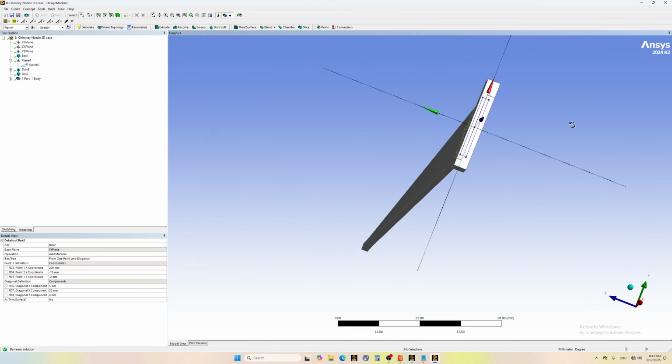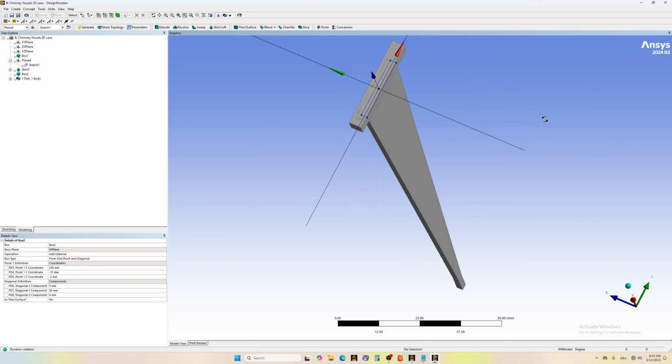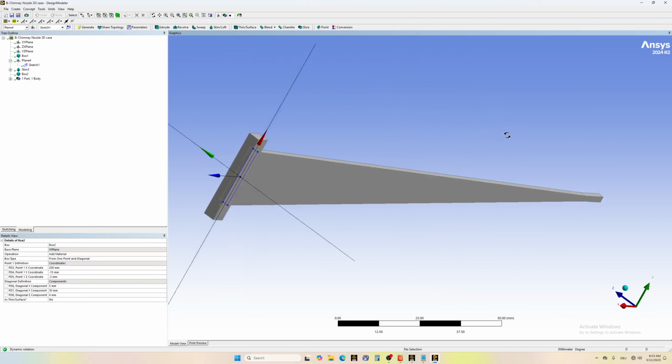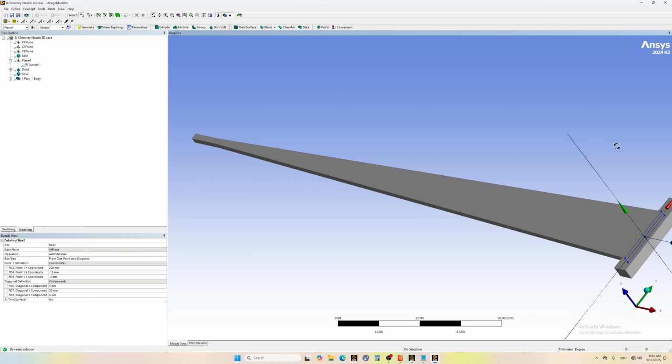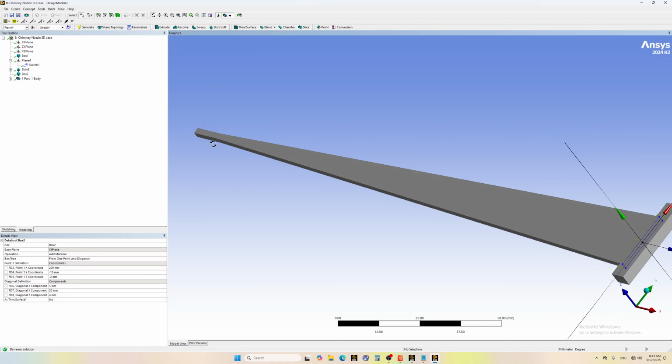You see it like this. So this is pretty much the entire nozzle. Keep in mind that it's very important to have this section about 1 centimeter. If you make it too short, the flow will be destabilized very fast, and even if this part is very long, it's possible that the density profile will be distorted.